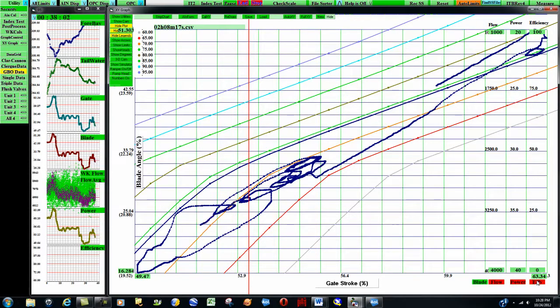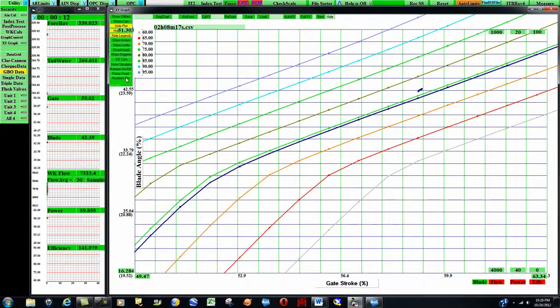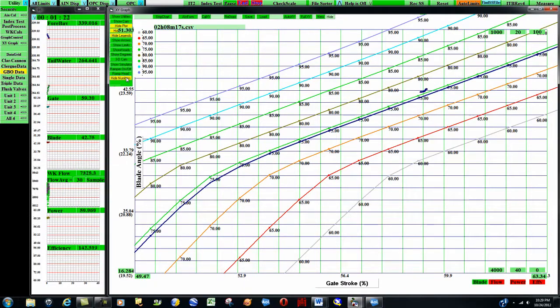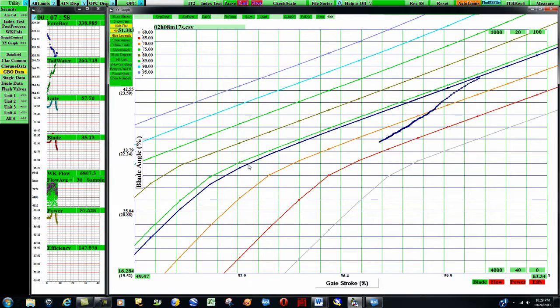This list of heads shows value and color to identify the head levels that define this 3D cam. Clicking the Numbers On button displays and hides identifying values for the Kaplan 3D cam curves to identify which is which. This cam surface has 8 blade to head and gate profiles at 5-foot intervals. The heavy blue line is the best efficiency on-cam line for the existing head. To show how the best efficiency on-cam line behaves as head changes, the index test box has a simulator with a head ramper as a graphic tutorial aid.